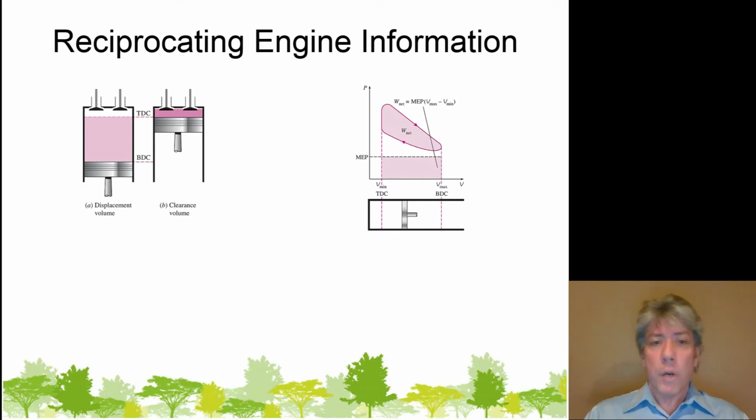So it's a 2.0 liter engine, and all that means is not that the volume when the pistons are all down is 2 liters, but that the displacement volume, the amount of volume that's displaced, is 2 liters, or thereabout. It's probably rounded off a little bit. And of course there's some manufacturing imperfections as well, but nominally it's a 2 liter engine.